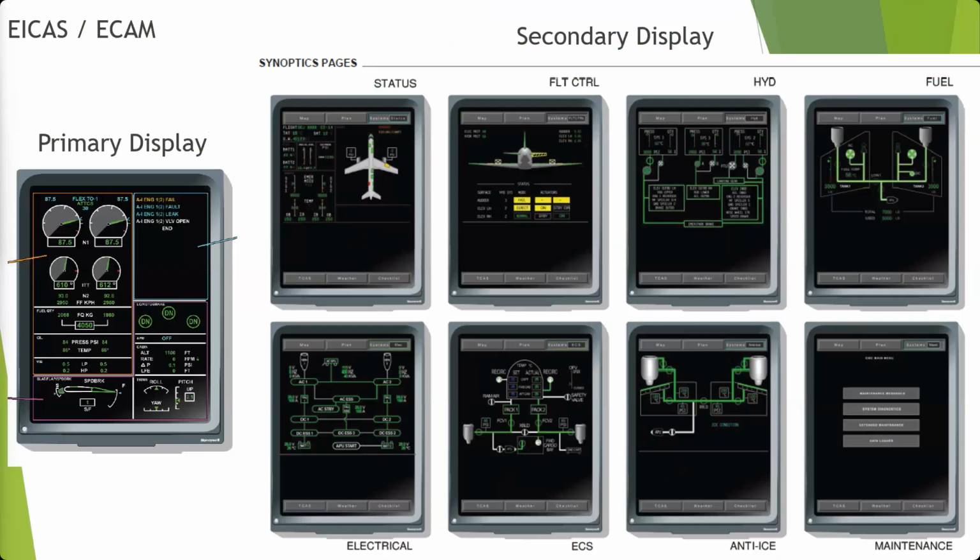They'd go to adjust it, and it popped the circuit breaker. The crew turned around, pushed the circuit breaker in, and tried to adjust it again. It popped the circuit breaker again. They did that over and over again. They didn't fry it. They stripped the threads on the screw, the big shaft that adjusts it. The thing that holds the horizontal stabilizer in a certain position wasn't holding it anymore, and it was able to just flop up and down. They lost the ability to control pitch of the aircraft.